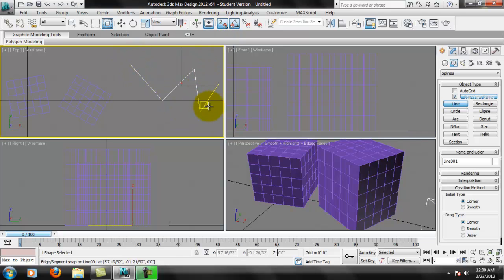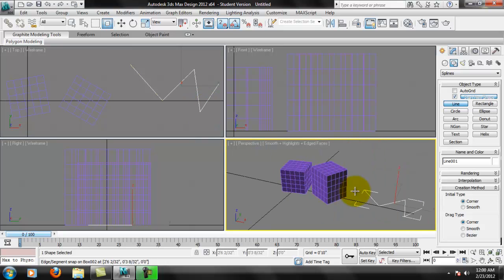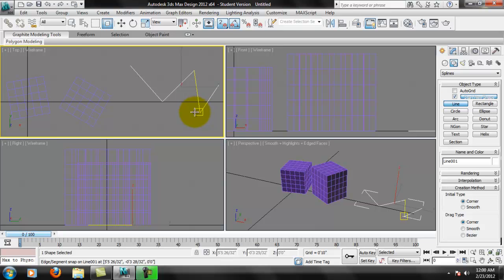Notice that snaps there. If I see that in the 3D view, you'll see that as well. See that snap over there. So that will snap to the 2D. Notice on a 3D object, it's only going to snap to the bottom. So 2 will only snap to anything that's on the plane. So anything that's resting on this XY plane will be affected by the 2 snap.